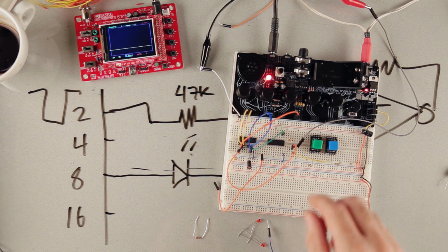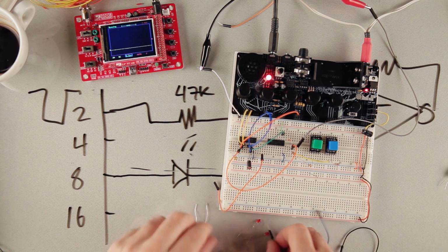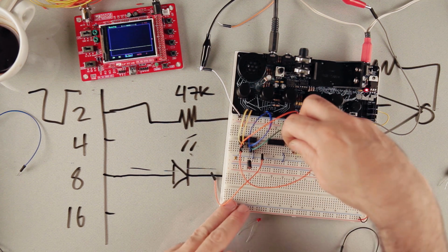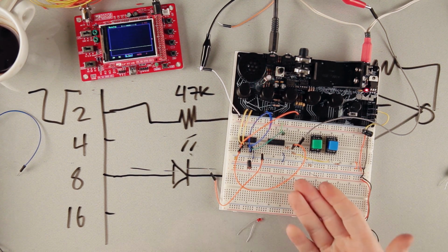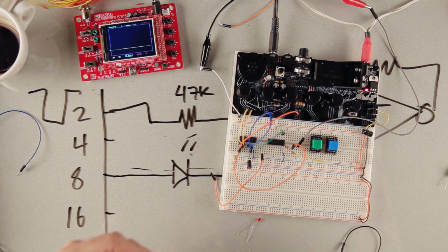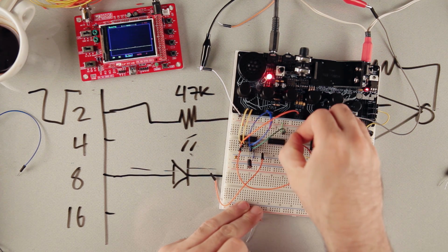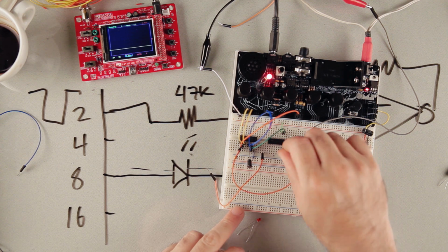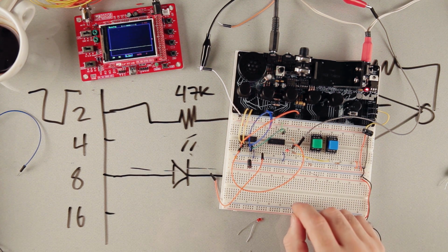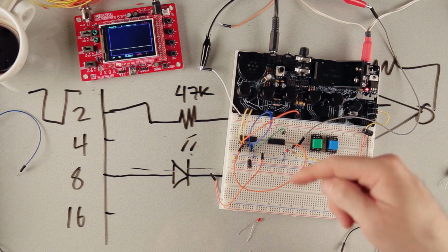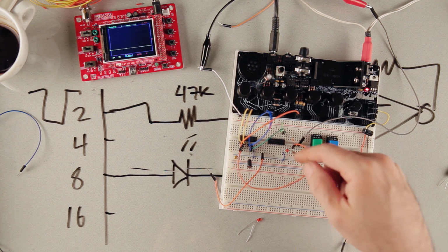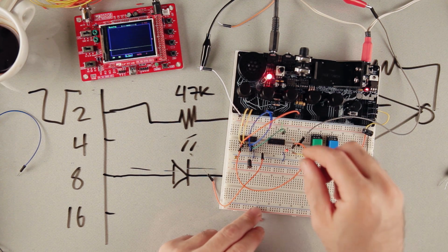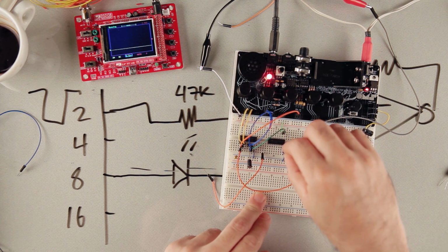Here's the divide by 2, and I'm going to take, so here let's listen to the divide by 8. So it's counting to 8, then it's going high, low. So again, here's the divide by 2, but then I'm going to take this LED and I'm going to plug that in. So it's divide by 2, now it's divide by 8. And if we turn it the other way, then it will reverse the phase.